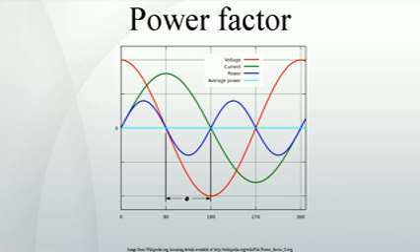In operation the moving vanes take up a physical angle equivalent to the electrical angle between the voltage source and the current source. This type of instrument can be made to register for currents in both directions, giving a four-quadrant display of power factor or phase angle.